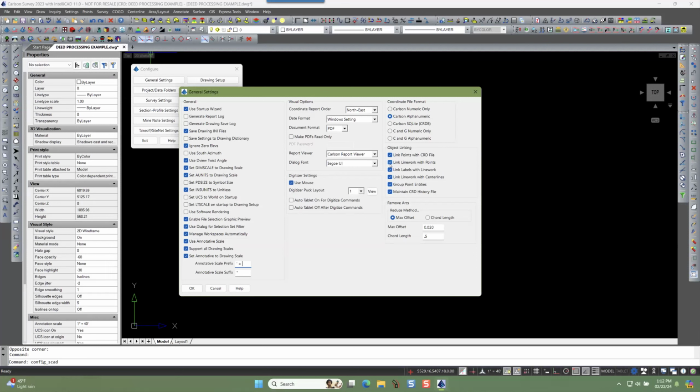Now, when you move a point, it's going to recognize that they no longer match, and it's going to pop up a little warning message. So that one is less crucial than it used to be. But you can see how you might want them to be either on or off, because some people like to work with points. They bring these points in, and then if a point gets in the way, they like to just, while it's in the drawing, shove it out of the way, move it slightly from where it is, and then know that they can go back to the coordinate file and redraw the point at its original